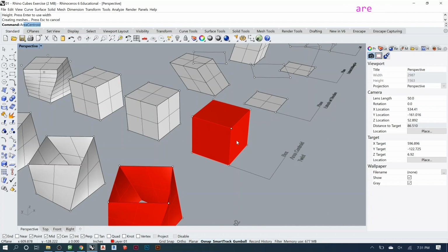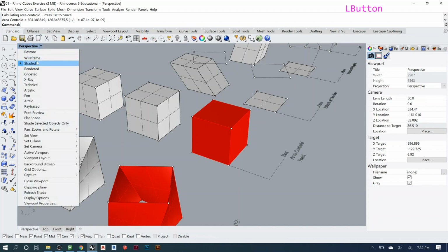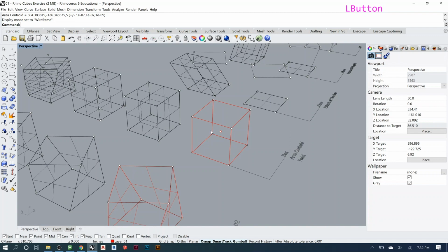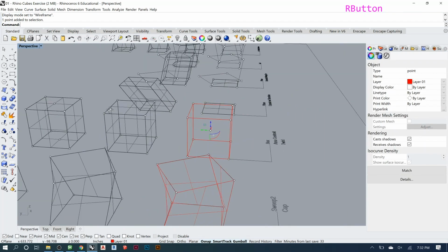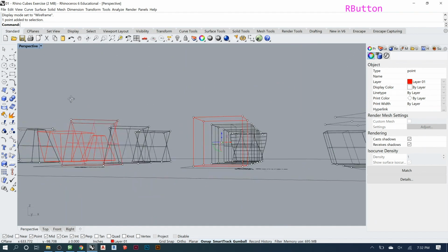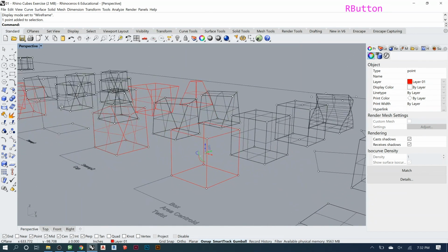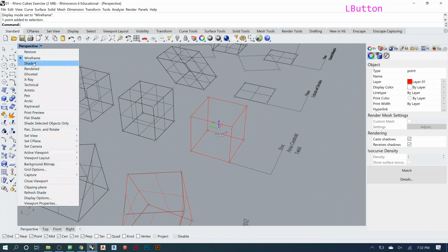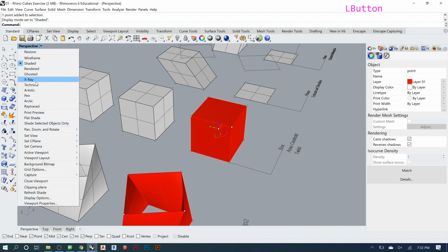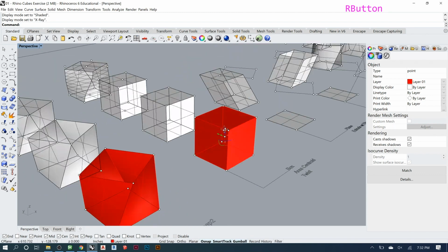Now you're going to type in AreaCentroid. It says this one, and hit enter. And it looks like nothing happened, right? But if we go to wireframe mode, you'll see that there is this dot here now, which didn't exist before, but we do have it over there. See, it's right in the middle. Now what I did here is I used the twist command. So we can go back to shaded, or you can use X-ray, which is kind of in between.